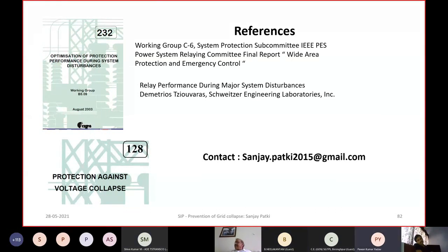Actually, we do not see any current in the REF circuit. If there is a current during a through fault, it should reflect some minor amount of current in the loading also. Yeah, unless you have a disturbance record, you will not be able to see how much current has actually flowed in the operating element of REF. You will not be able to see that in normal condition, unless you have a DFR which gets triggered by a fault. But sir, theoretically, it should not flow in the REF circuit.